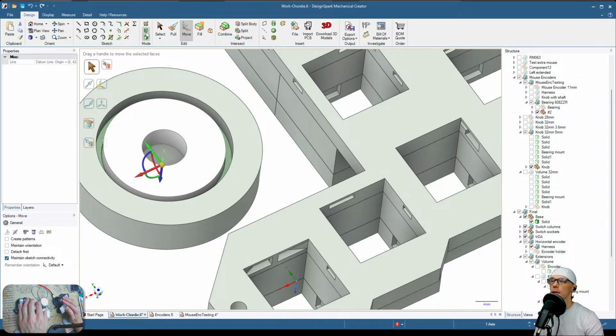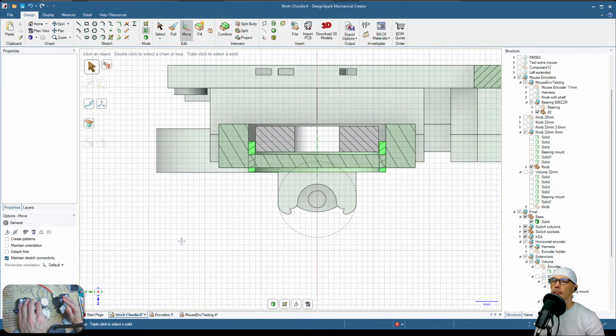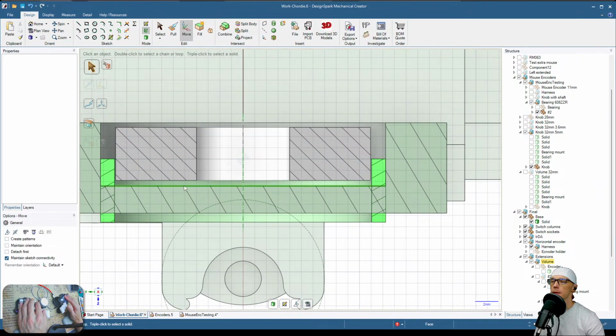What I'm trying to do is this part over here, because if we make it all the way down, if we just cut this piece, then it's almost impossible to remove the bearing later on. So if you make the part that is actually holding the bearing short like this, 2.4 should be okay. Might be too much. We're gonna find out on Monday.